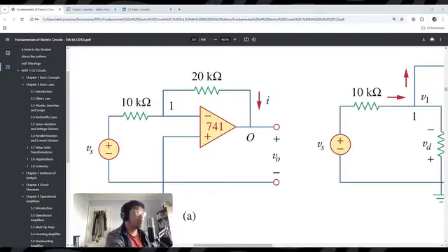So we see that we have the op amp. This is a universal op amp, although you could use an LM741. A popular one for guitarists is a JRC 4558. That one is one of the best sounding, has the best total harmonic distortion, or THD. Some of these terms you don't have to know just yet. Just know that it sounds good and warm to the ears. And so we have this universal op amp, a VDD rail, a VSS rail.